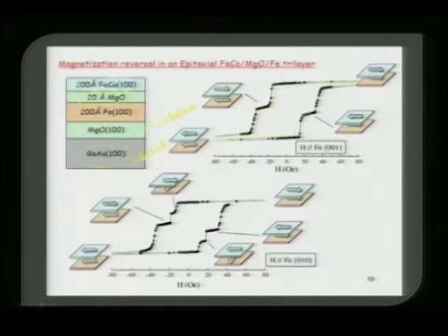So at 80 oersted here and 80 oersted here, in both cases it is ferromagnetically coupled, but in the staircase area they are antiferromagnetically coupled, and this is a true property of a tri-layer TMR device.